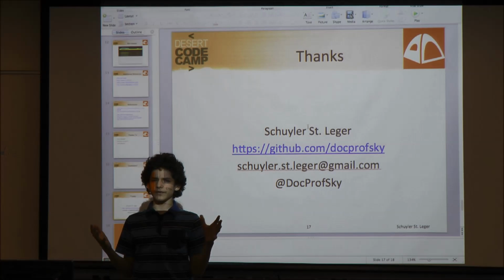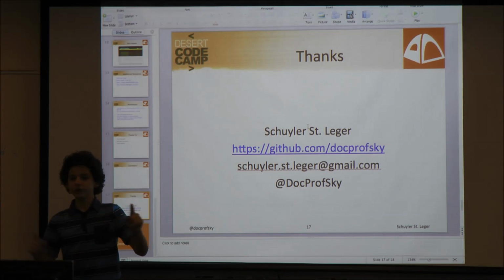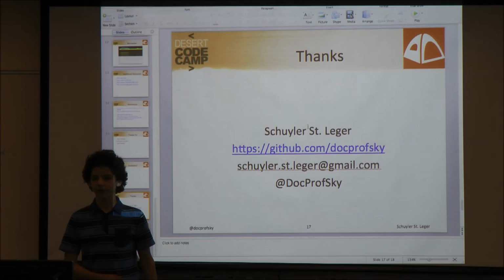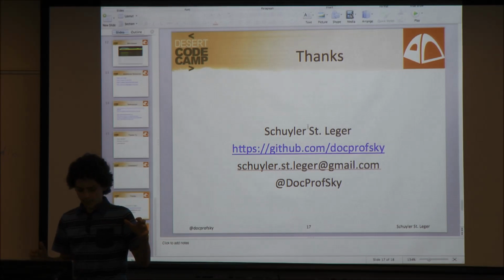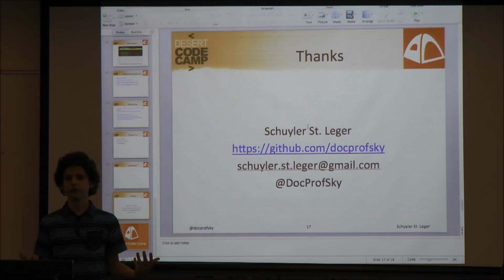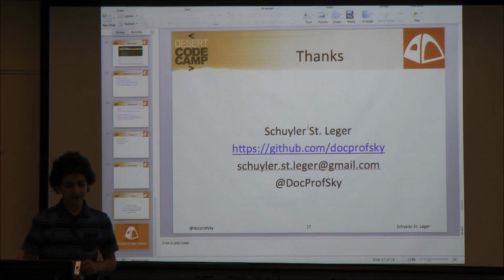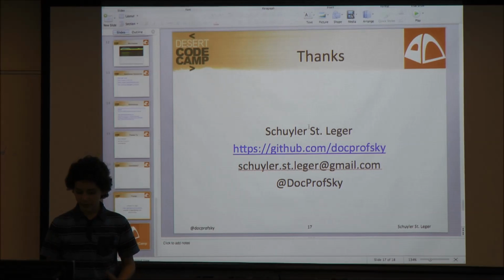With the ISM bands, I looked this up online briefly. I'm not the absolute authority on this, so find this out yourself, and I'm not responsible when the FCC comes knocking on your door with the white vans filled with $3 million of equipment. But as far as legality goes, if you're in the ISM bands and you're transmitting not too high power and you aren't interfering with anything, you're probably fine. If you're using the Raspberry Pi as an FM transmitter, make sure there's nothing on the frequency you're transmitting on before you transmit. If you look at the Pi, you'll see a lot of harmonics, because it's essentially using noise, and they know how the noise is generated.